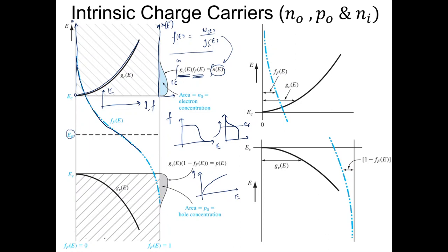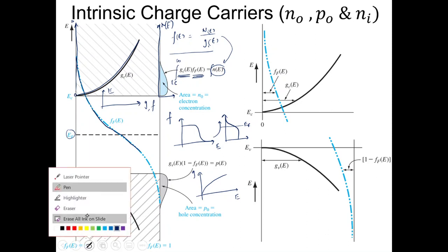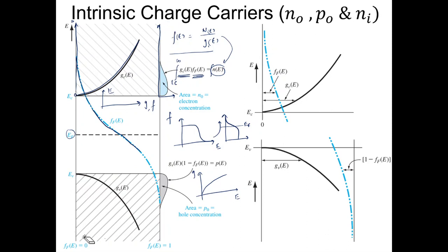So this is E, and this is N. What it shows is that the electron concentration starts increasing. It's maximum at an energy level slightly higher than the conduction band, and again it falls as you go higher and higher in the energy level. It falls because the probability of occupying any state would fall as you go up in the energy level.